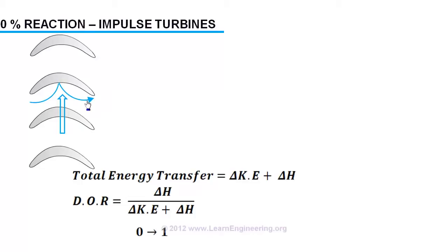We know along the blade enthalpy doesn't change. Along with enthalpy, temperature will also remain the same, because enthalpy is a direct function of temperature, assuming steam as an ideal gas. There will be a slight drop in pressure, but you can almost assume pressure is the same across the rotor. The only quantity which changes here is the velocity.